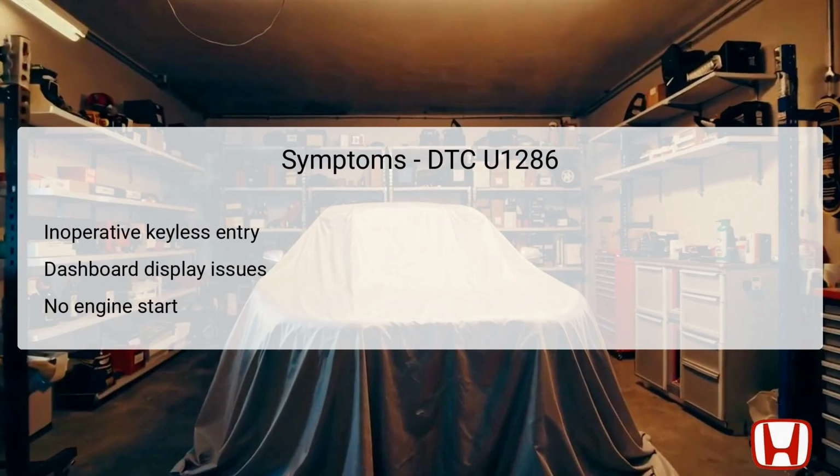When DTC U1286 is present, symptoms may manifest in several ways. One of the most noticeable issues is the inoperability of the keyless entry system, meaning the driver may not be able to unlock or start the vehicle without a traditional key. Furthermore, the dashboard display may exhibit erratic behavior or fail to show crucial information accurately, such as speed or fuel levels, due to the breakdown in communication with the gauge control module.